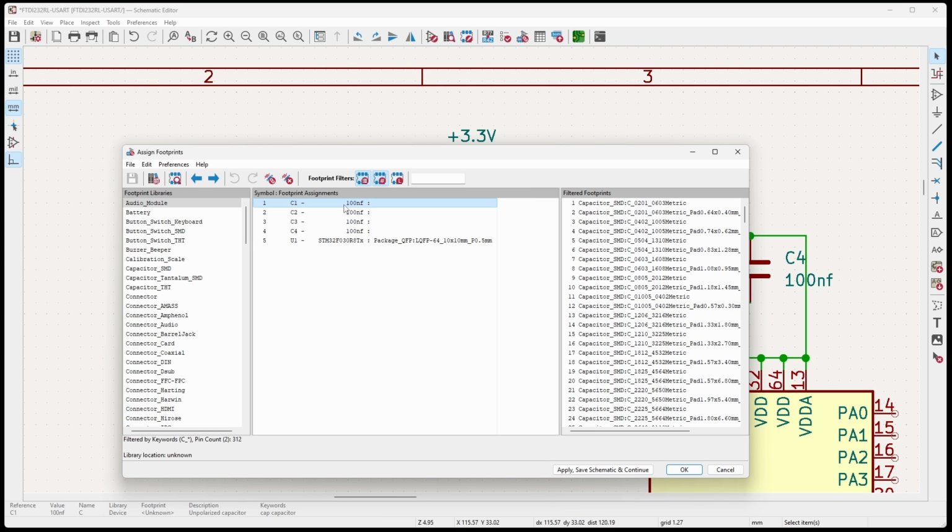If you're going to be making the footprints for SMD, which I suggest doing because this is the easiest way to have the boards assembled by a manufacturer, or if you're doing it by yourself and soldering them by yourself, you'll want to choose the component that is economical for the production size or what you might have on hand. In my case, I have the 0805s on hand because I use this quite a bit in my other projects and circuits that I sell. And it's also a lot easier to hand solder if you need to.